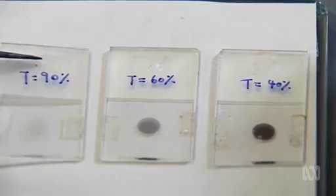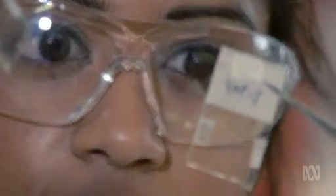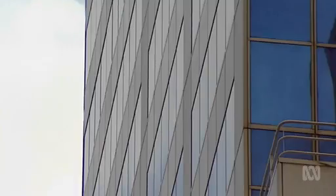So, in this lab, we can take these short nanotubes and we can make films that have greater than 90% transparency. So if we, for example, put that on a window or put it on any flat surface, the wall of your house or your car, you wouldn't actually even know it was there. We could make solar panels out of the windows. You can only do that with really thin, flexible electrodes, and the short nanotubes give you that opportunity.